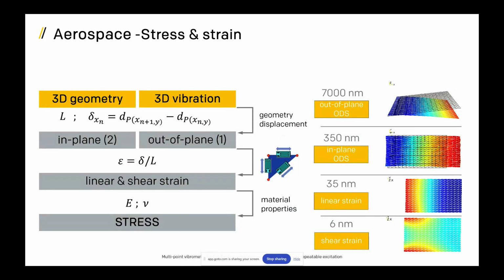So talking about strain a little bit, we can do two different things. We can map the strain across an object using our 3D system. So with a 3D system, if we run an excitation for a device under test at a given frequency, maybe 5 kilohertz as an example, we quickly move the 3D sensors across the surface and map it all out. That will give us the displacements of all of the given points on the surface.